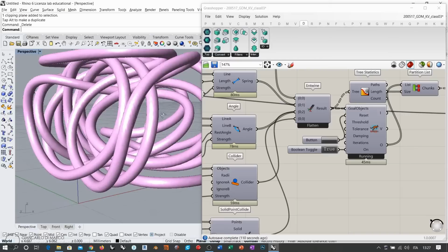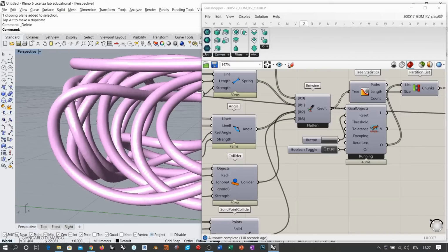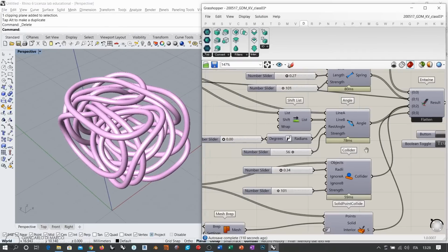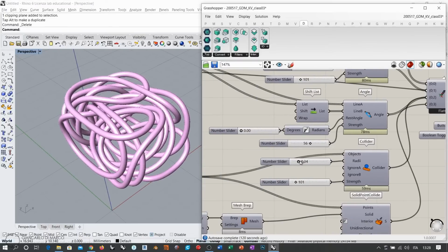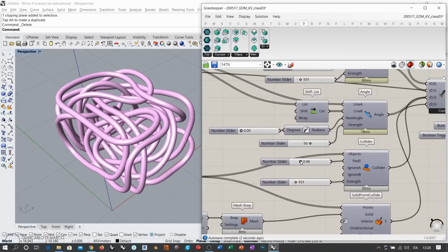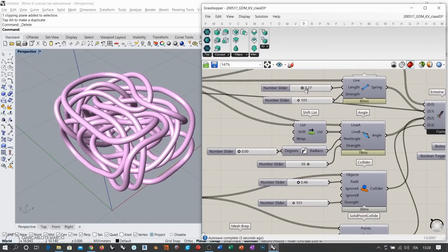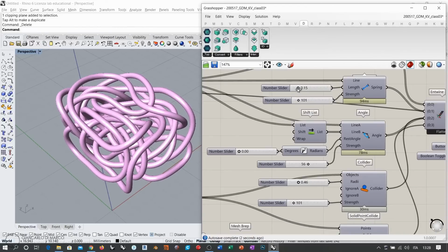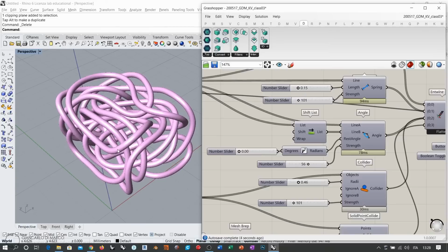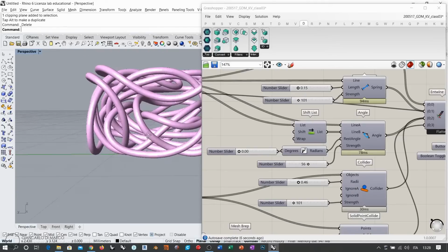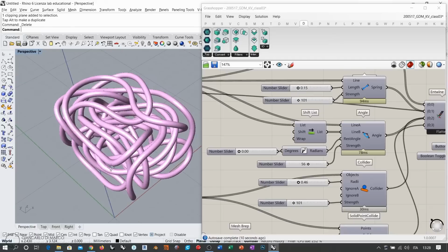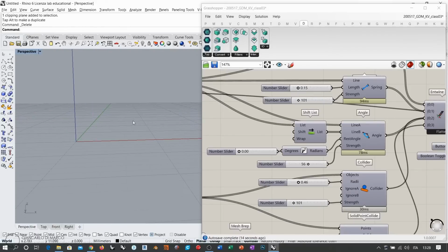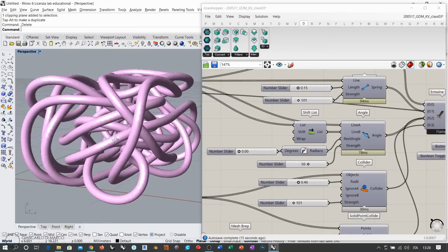It works. It doesn't self-intersect. Well, here it's getting too close, but I think that this depends also on the value that I'm using here. I can increase this to try to avoid self-intersection, but also I forgot to decrease the length here. That's why you saw that some self-intersections were occurring. But you see that I managed to solve the situation. I acted quickly, so I could recover from the self-intersection in that case.